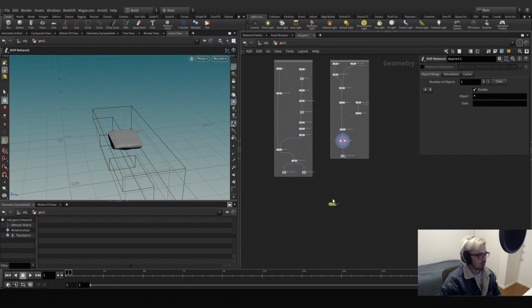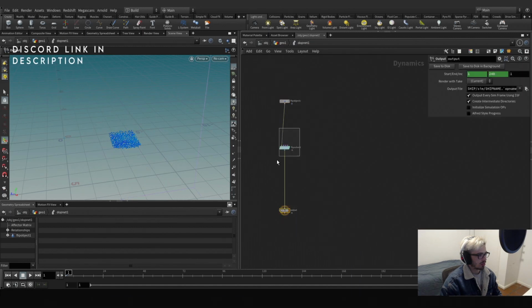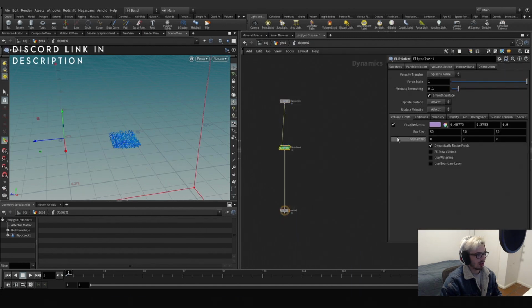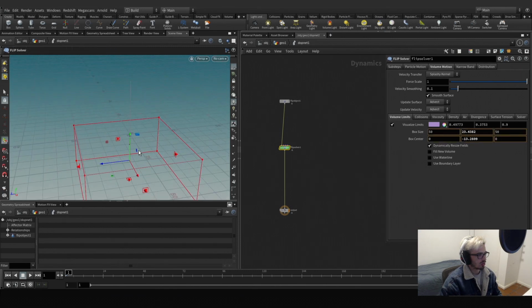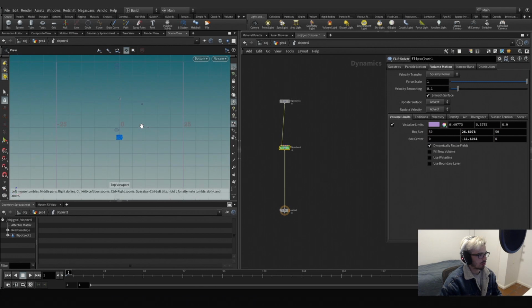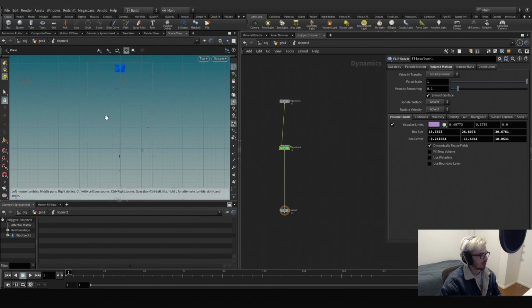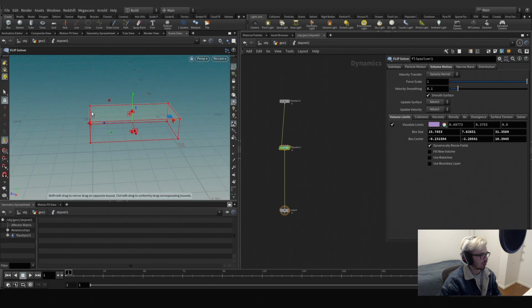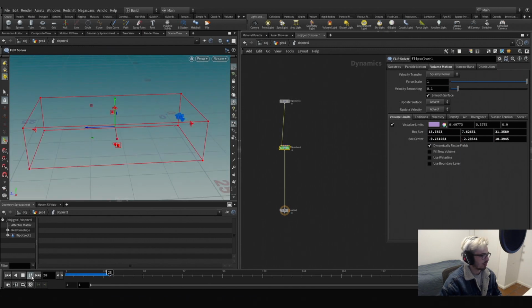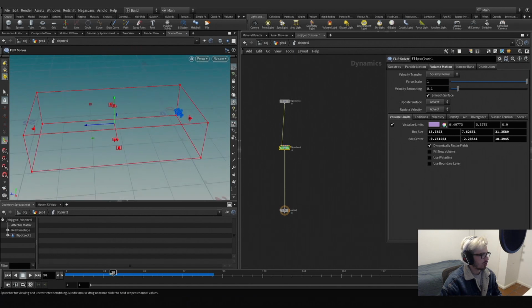So what we want to do is, in this case, to have our bounding box, this one on the volume motion, the limits, kind of similar to where we need to have our particles. So let's add space 2. Let's shrink this here. Let's also shrink this one here. Remember, we're going on the z-axis, so maybe we need to have these two guys together, like so. So basically what I did is to displace this box where the water is going to go, so around here. So we press play, nothing happens, but we only have an initial velocity, which we added before.